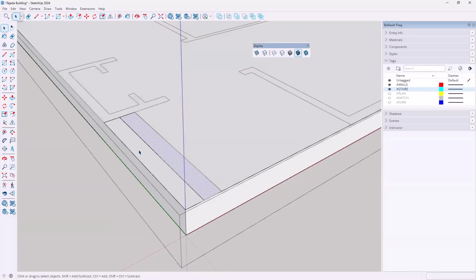So I'm going to take this surface and push pull it. I'm going to type P, click on it and take it straight down. This needs to go down 12 inches, so I type in 12 and enter. Then I come over here, still in my push-pull mode, give that one click and take that down 6 inches. So I type 6 and enter.